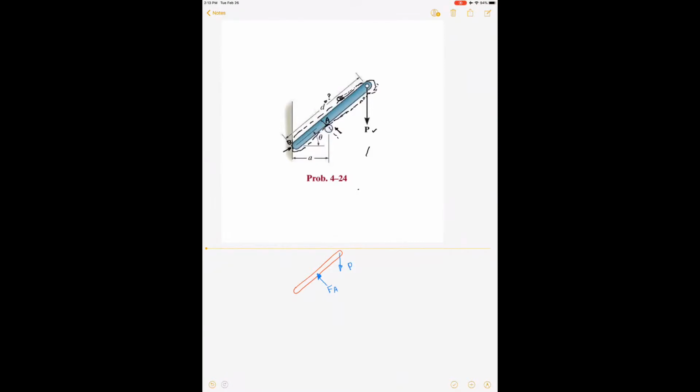Now continue walking on the border. The next thing I can cut is the contact point at location B. Let's call it FB. Again, that's pretty much the same contact, frictionless, except the normal direction would be in the positive X direction. Now continue walking back, and then I'll go back to my start point, and I'm done with the surface forces. Now the body force, according to the question, you can ignore the mass of the beam, so there's not going to be any body force.